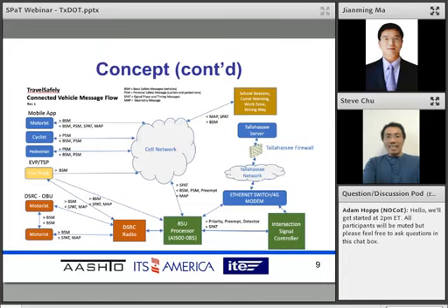If you look at the diagram, from the intersection control side, the SPaT messaging is sent through what we call an RSU processor. From there, the SPaT messaging is sent out in two directions. One direction goes straight to a DSRC radio. The other goes straight to a cellular network, which is hosted by a third-party network. Any information sent to the DSRC radio will broadcast straight to the OBU. If your vehicle has an onboard OBU, it will take that information and transmit it to an app.